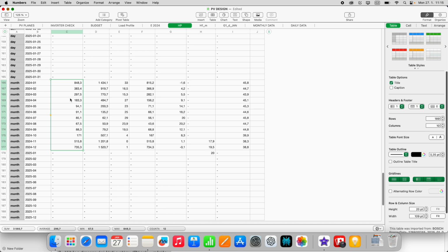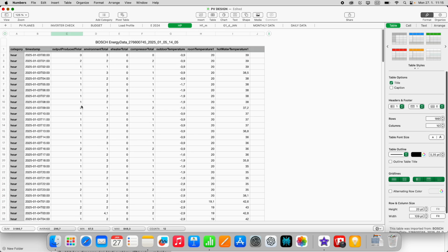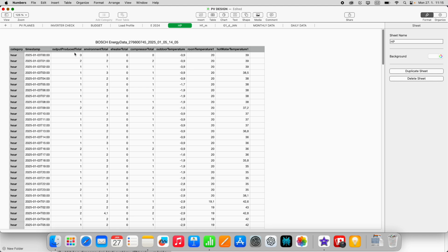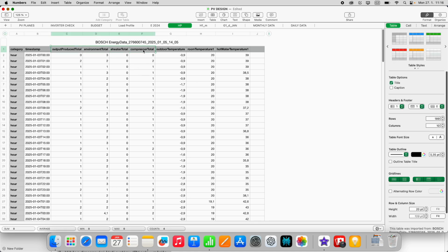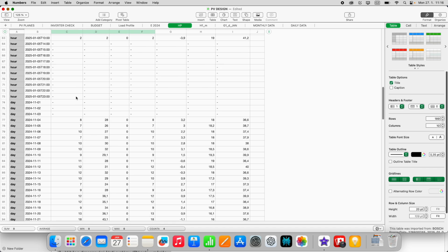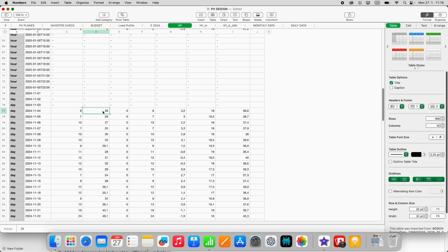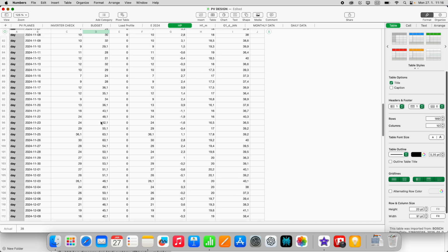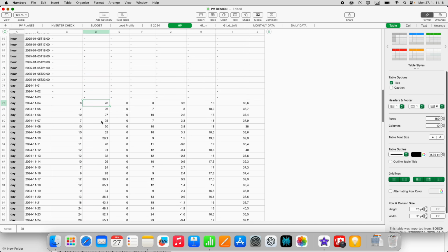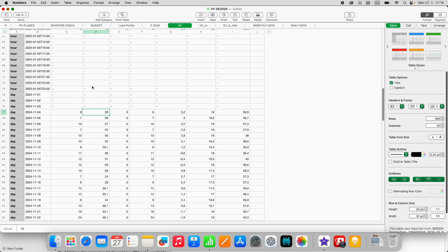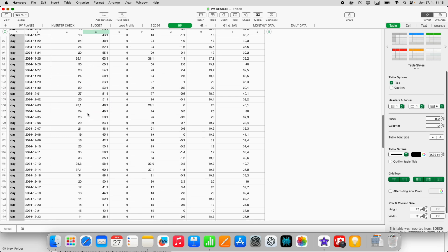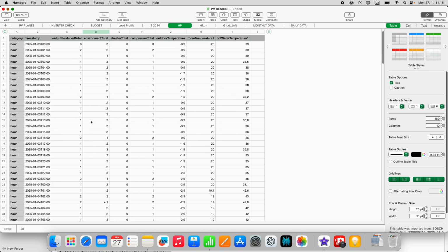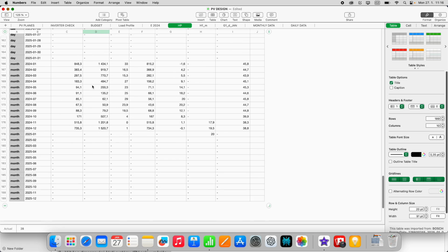And so what we get actually logged here is the output produced total, environment, heater, compressor, outer temperature, room temperature, and hot water temperature. Now, which of these four values are interesting to us? Well, it's the first one, because although this value is higher, it's actually based on the concept of the heat pump. And so by dividing those two values, you could get the COP value, the actually experimentally measured COP value for each month here.